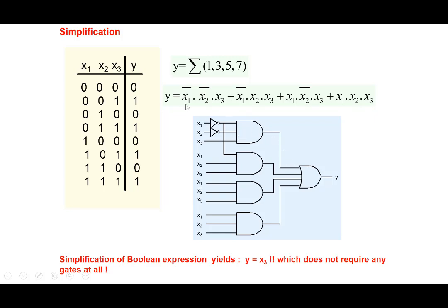So when you don't have an optimized expression, the signal also encounters more delay here. So the circuit is more complicated. The path of the circuit from input to output becomes longer. So it encounters more delay also. So the circuit becomes slower also. So you end up losing not just in terms of the cost point of view that the circuit is more complex, but you end up incurring a performance penalty.